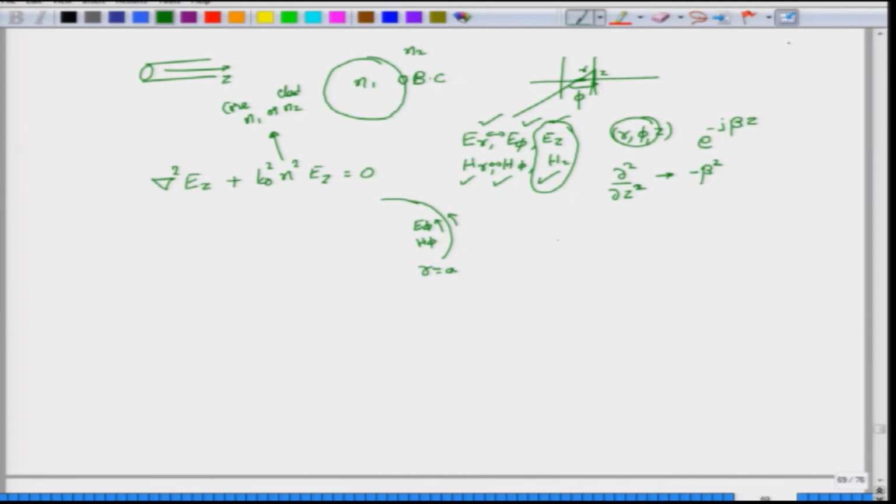So if you imagine that you have some kind of a cylinder, then there will also be Ez and Hz components. I have not shown it in exactly the same way that I have plotted. So you imagine that this is a cylinder, and as you move around, this would be the E phi component, or you move along the cylinder, that would be an Ez component, but it is still parallel to the interface itself. However, the radial component would go from one medium to another medium and actually be perpendicular to this surface. So this would be the r equal to a surface that I am looking at, and clearly the Er component here and the Er component on this side are normal components.